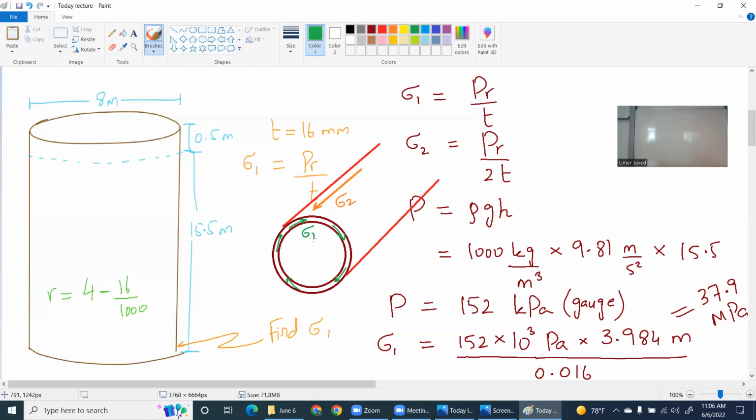Another thing you have to realize is that these are rough estimations at the end of the day. They always give you ballpark figures. A thin pressure vessel calculation will just give me an idea about the stresses. If I have to really design a cylinder, I will have a ballpark figure, but then I will put it through rigorous ANSYS or similar tests. These are the couple of ways I'm trying to answer the question.